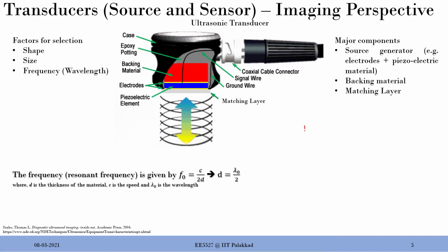So let's put the two electrodes here. These are the two electrodes, and you have a material lying here, and this is the distance d. Now these two are fixed, right? They are not allowed to vibrate because those are the electrodes and they are fixed, like rigid bodies. But we know that for resonance to be created, ideally what we want is to create a standing wave inside, right? Go back to the lecture. A standing wave is what actually appears like resonance, right? So what we want to create ideally is a standing wave here. So how to go about it?